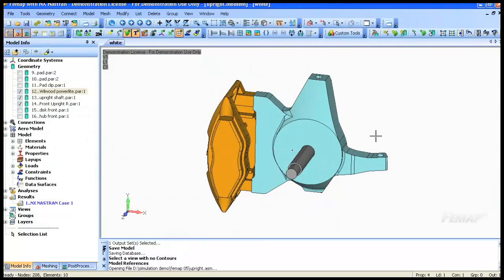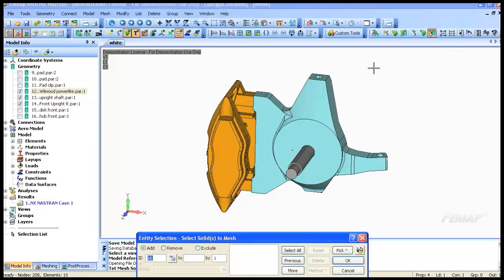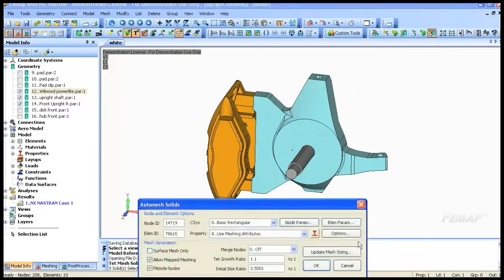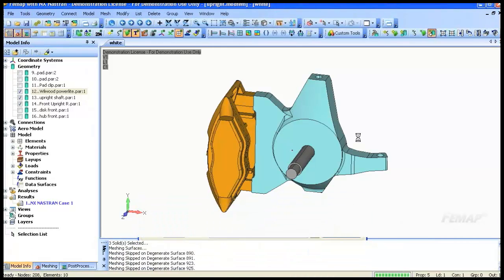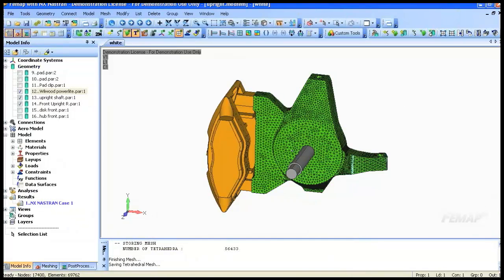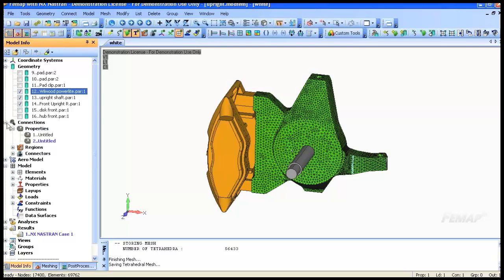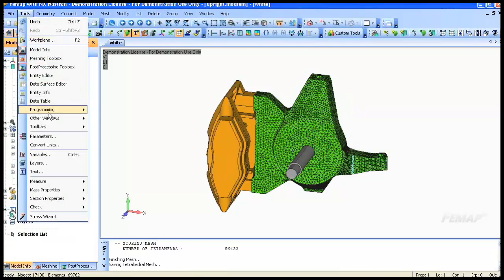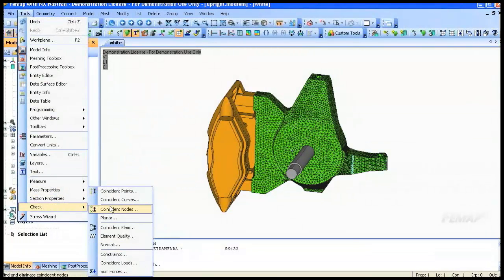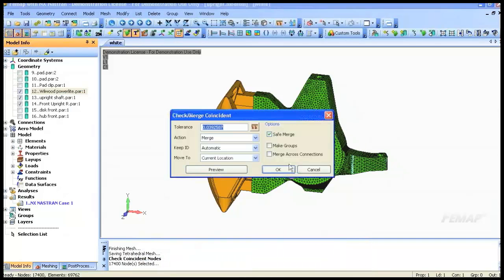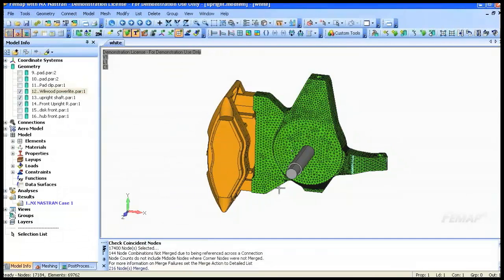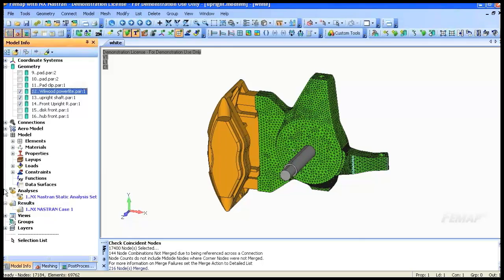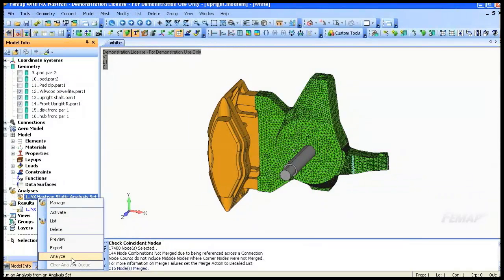What you need to do now is mesh, and resolve the analysis. So if I just click the mesh, pick the 3 parts, I turn mid-side nodes off again. Okay, all our connections are still set up and everything. We'll just do another move to reconnect the bolts back in. All we should need to do is just say analyze.